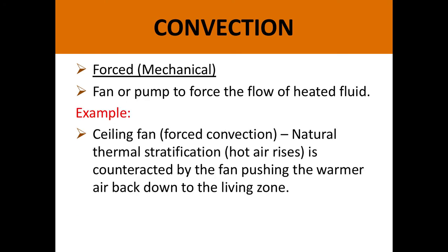Now, forced or mechanical convection is most of what we use now in modern day furnaces and boilers. We use a fan or pump to force the flow of the heated fluid. Okay, so a ceiling fan is an example of forced convection. Hot air rises and then is counteracted by the fan pushing the warmer air back down into the living zone. That's why you'll see a lot of ceiling fans in a lot of commercial buildings with big entranceways.